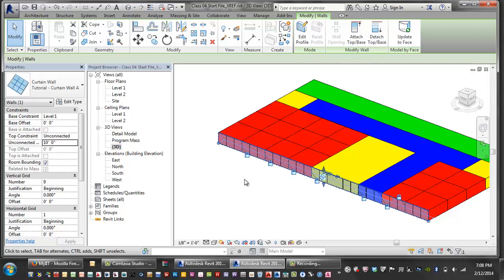Get my marker. And in most cases, you're either going to build the curtain wall as if it sits on the slab, and then you're going to go up to the next slab and then seat it so it's a gravity system. Or I'm going to go ahead and load it and hang it off the front face of the slabs themselves.